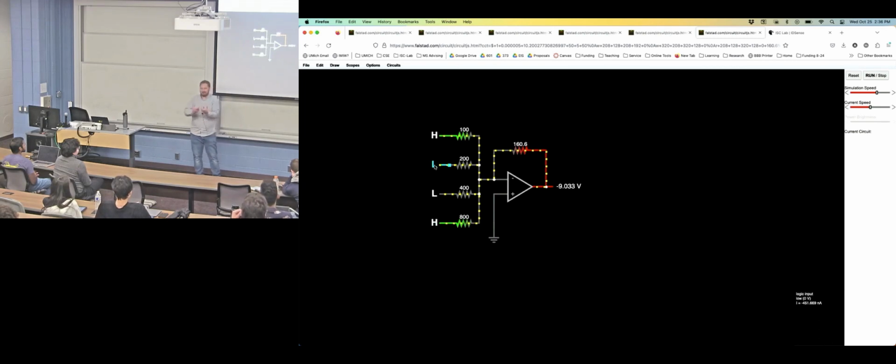The way to mitigate that is the resistor values will essentially be powers of 2, so you put 100 ohms here, and in your manufacturing, you stack one, and then you put another 200, another 100, another 100, link them together. So when they are fabricated, they're as close as they can be. Yeah. I was going to say also cost, because if you have different types of resistors, you have to order all of these different types of... Well, it's true, but we're in silicon land. So you're just fabricating them on chip. So we think about the area cost and the linearity cost more than we think about the purchasing cost, I guess.